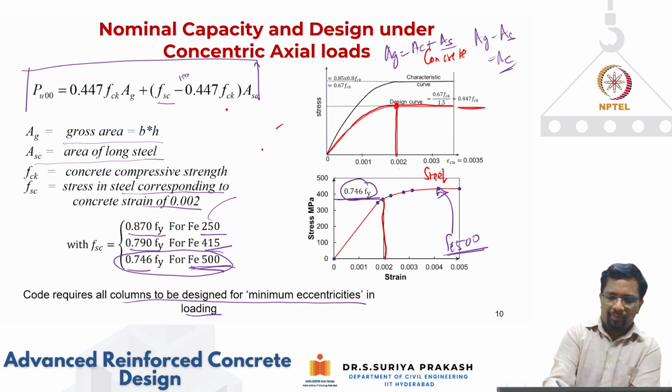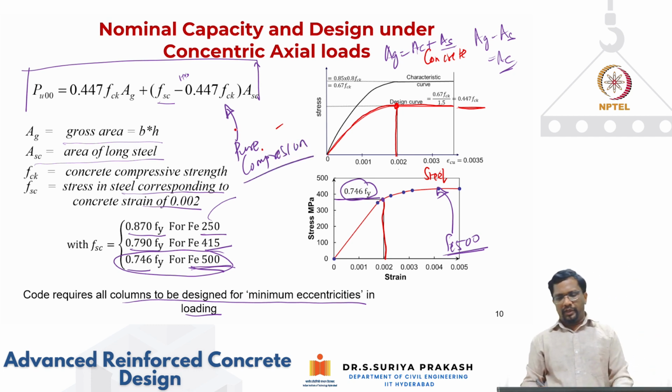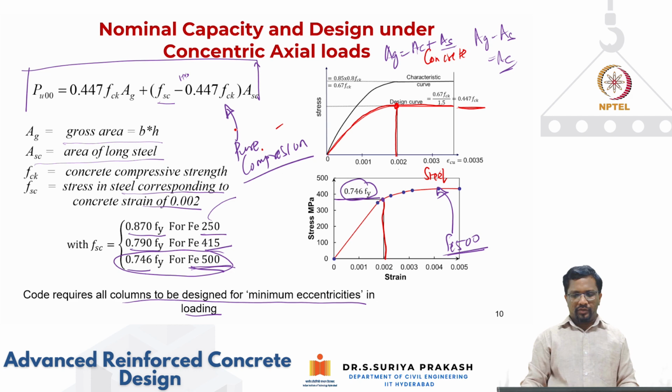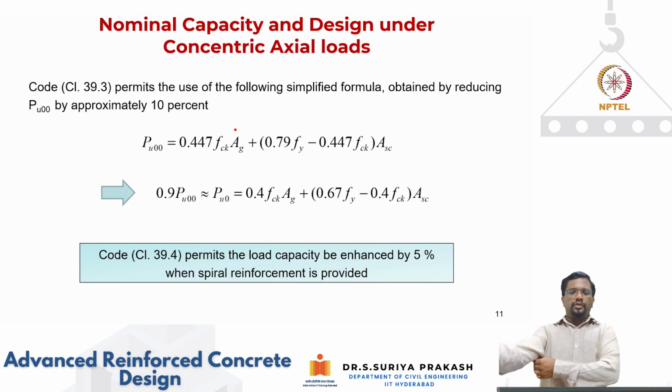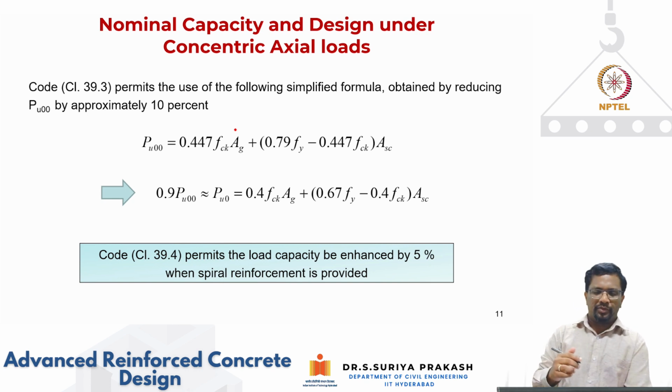So this is for pure compression, the capacity that I can use for calculation, right? And again, this equation is derived for a failure strain condition of 0.002.